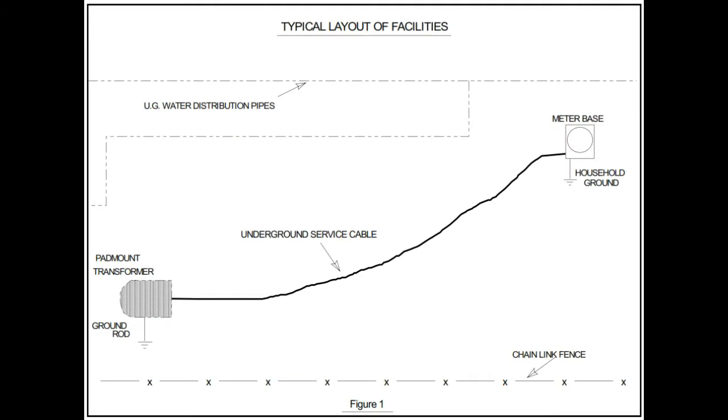What we have learned as a matter of practice is you do not usually need to know the exact path of the cable. The transformer and service locations are known, and where you want to try to get readings without first scoping the cable, what we have done is to go approximately 2/3 the distance from the transformer to the service, be that a street light or a customer's meter base. There we start taking our readings.